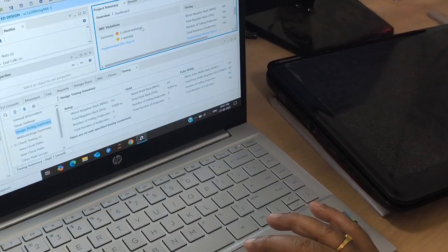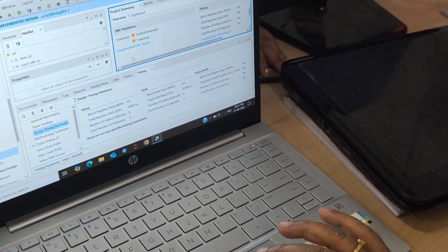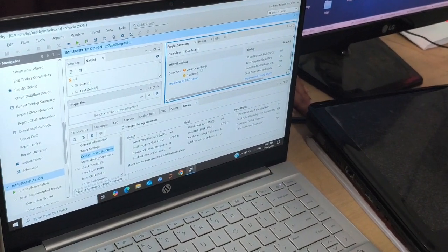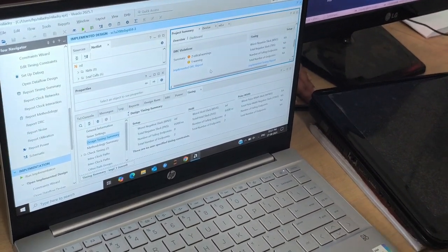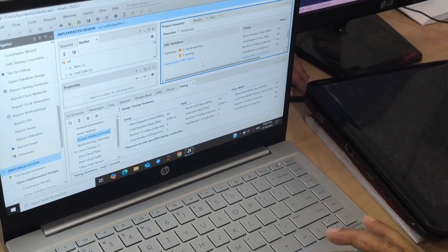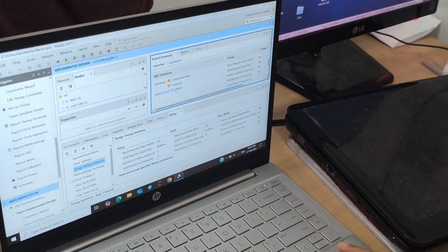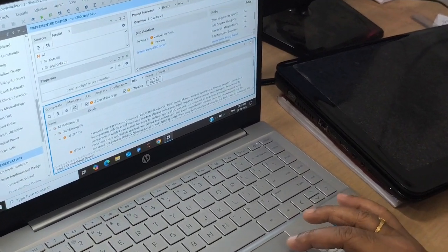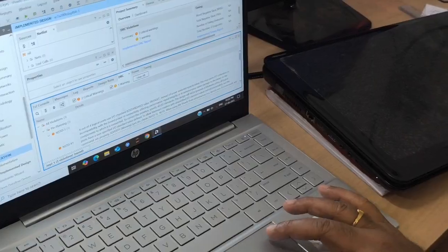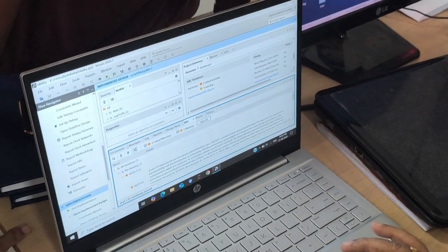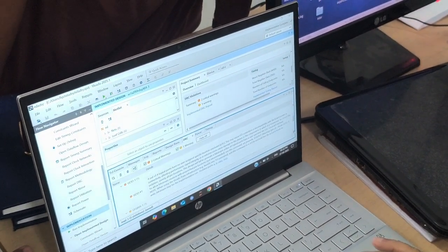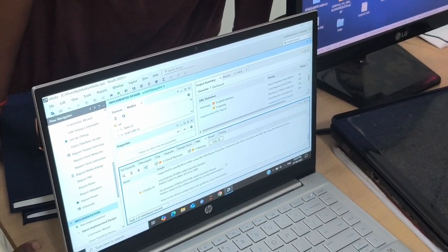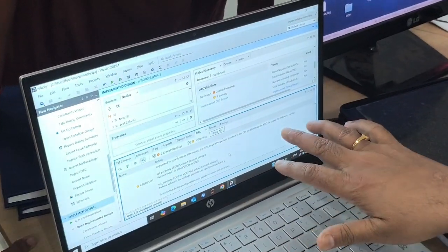So see, 2 critical warnings are there, 1 warning is there, but no error. Whenever there is no error, it is okay, but critical warnings sometimes may stop it from mapping into the real mode, so you have to look at the critical warnings. The implemented DRC report you can also see from here. These are the 4 out of 4 logical ports, IO standard and default. You can read these from here. They tell how they have mapped everything, the ground and voltage, which port is mapped and what the information regarding it is.